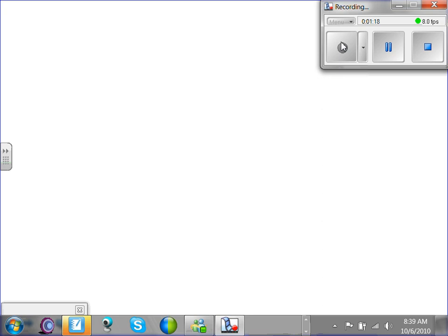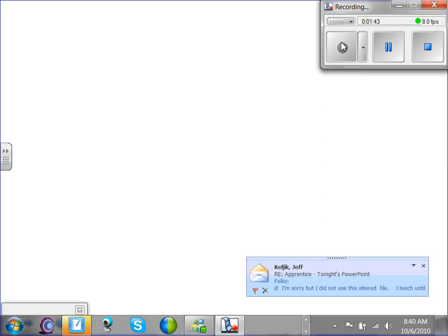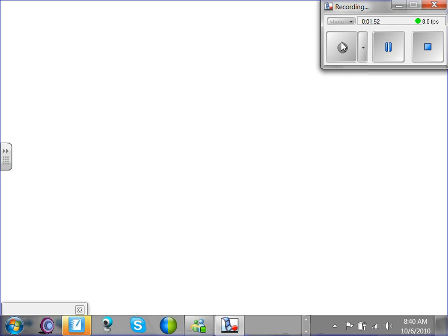Before we talk about continuous and non-continuous, does everybody know the definition of a continuous load? Brad? Spencer? Three hours or more. The equipment is running at that current for 3 hours or more continuously, right? There's one more that a lot of people miss, not just you guys: max at its rated amps. So if I have a piece of equipment rated at 50 amps, Eric, my friend, and it's running unloaded at 25 amps, that's not its rated amps. It has to be at its rated amps, which is most of the cases.